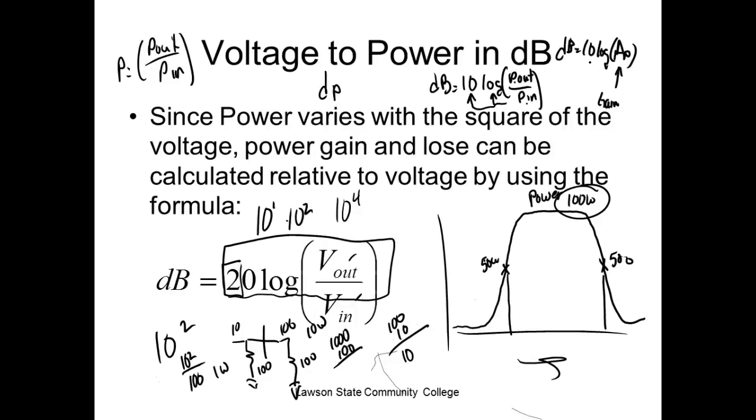But in communication systems, your impedances are going to match, right? They match those impedances so we can get maximum transfer. So your cable is 50 ohm cable. The input to your cable box is a 50 ohm input. All the amplifiers that they use are 50 ohm amplifiers. So what they do is they match, so that means 50 in, 50 out. Now this will work. It wouldn't work if I said 100 in and 10,000 out, right? Because now my current would be different on my output. So I wouldn't get the same current gain, right? Does that make sense?